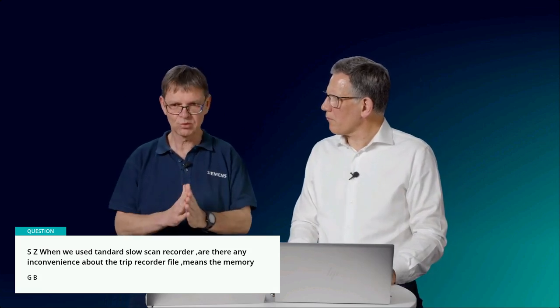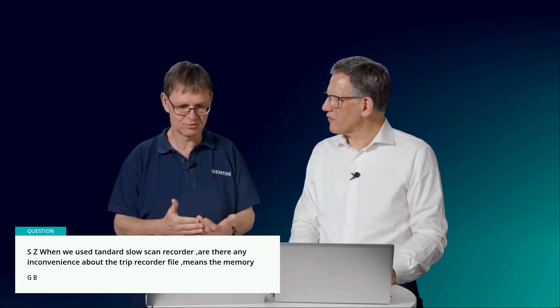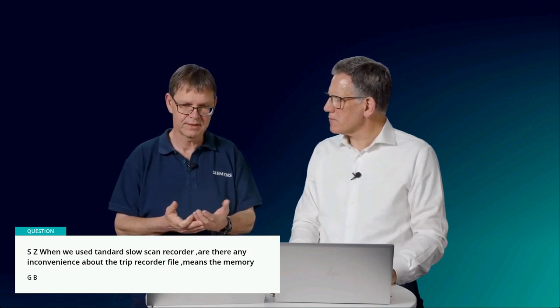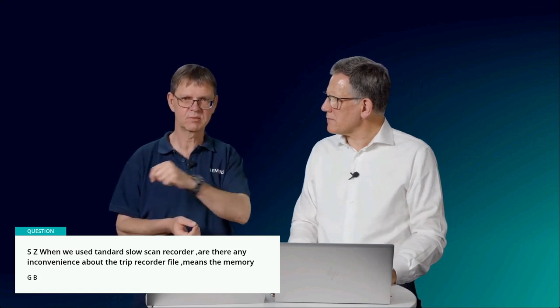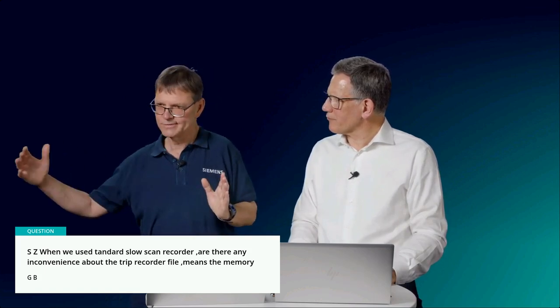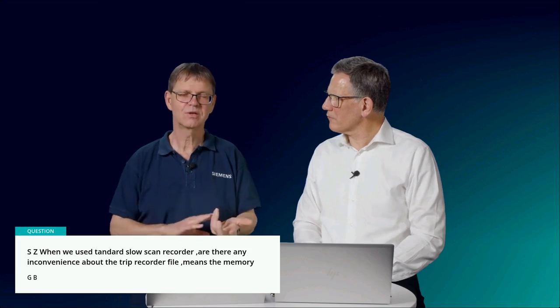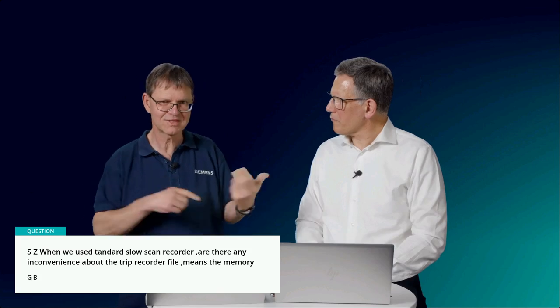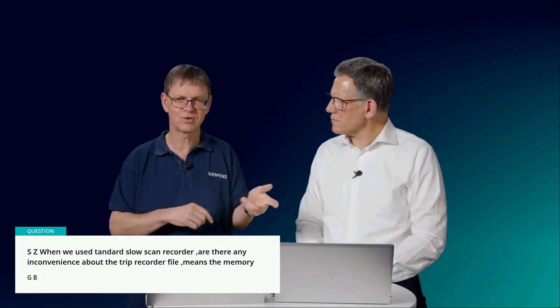And the idea of the slow scan record, I don't know if it was really clear during the video, is that you have only a few samples, one every 100 milliseconds, so you can register a long time, the full motor start, even if it's minutes, no problem. And the file size is relatively small, therefore you can host many of them. How this is internally organized with the memory, I'm not 100% sure. If we take away something from the standard recording, the fault recorders, if we have many fault recorders, or if we increase the memory for the fault recorders.